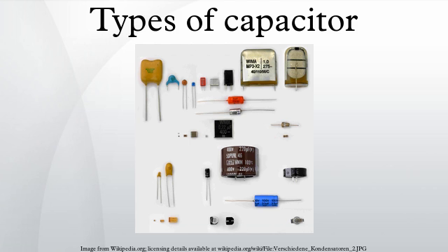Voltage dependence. Capacitance may also change with applied voltage. This effect is more prevalent in Class II ceramic capacitors. The permittivity of ferroelectric Class II material depends on the applied voltage. Higher applied voltage lowers permittivity. The change of capacitance can drop to 80% of the value measured with the standardized measuring voltage of 0.5 or 1.0 V.